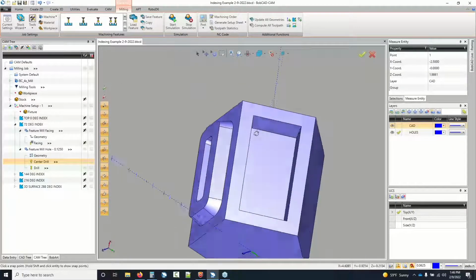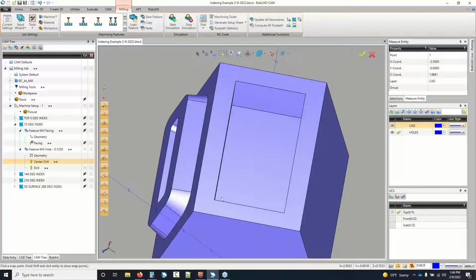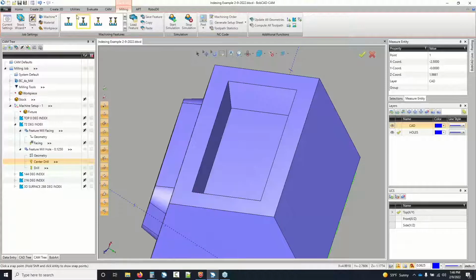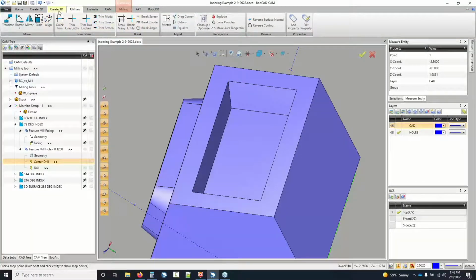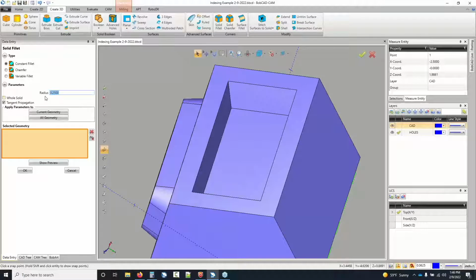So now what I'll do is this 2-axis pocket we got here. I made it with sharp corners, and this thing shouldn't have sharp corners. A quick update you can make is I'm going to use a 1/2 inch tool to rough it and a 1/4 inch tool to finish it. A 1/4 inch tool leaves an 1/8 inch radius, so I'm going to set my radius to an 1/8 inch.